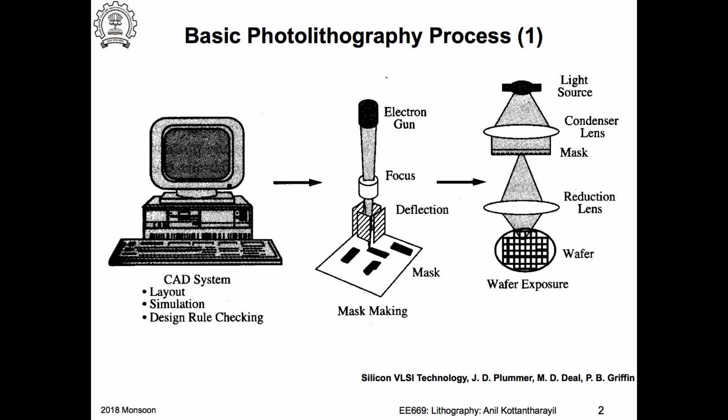In making the layout, there are design rules which say that this pattern has to be away from the next one by a certain distance. You can't violate this. So you actually do simulations to see whether the thing that you have designed conforms to the design rules.